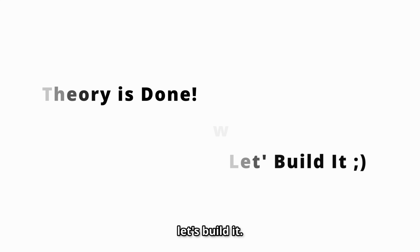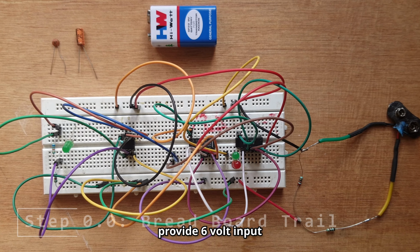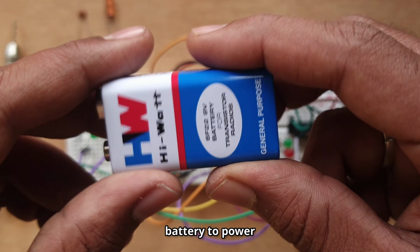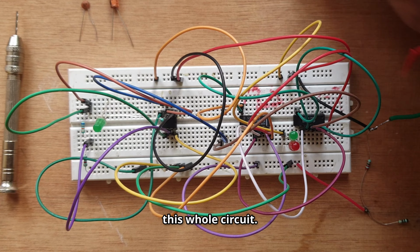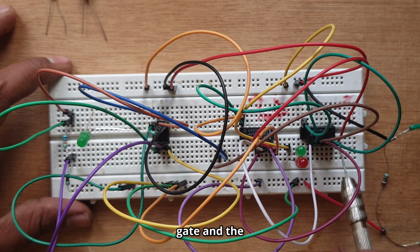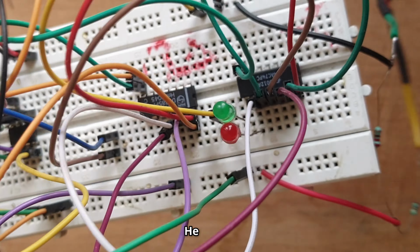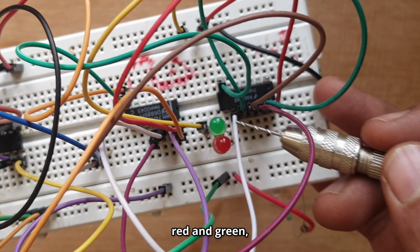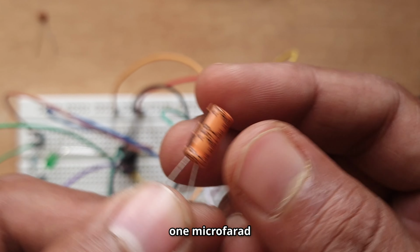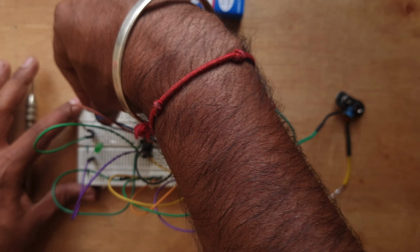Now let's build it. This is the voltage divider circuit, and I'm using it to provide 6 volt input to this breadboard connections. I'm using a 9 volt battery to power this whole circuit. This is the IC555 and this is the XOR gate and the D flip-flop. This together forms a toggle flip-flop. Here I'm using two LEDs, red and green, one for head and another for tail. At first I'll be using a 1 microfarad capacitor so that we have a frequency of 10 Hz.